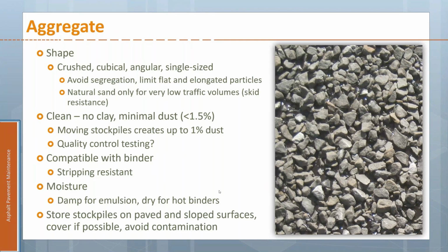So things to do, if you can, store your stockpiles on a paved or sloped surface to let it drain well. You don't want the aggregates to be too damp. You want to avoid contamination and, of course, dust. Dust is the number one issue.